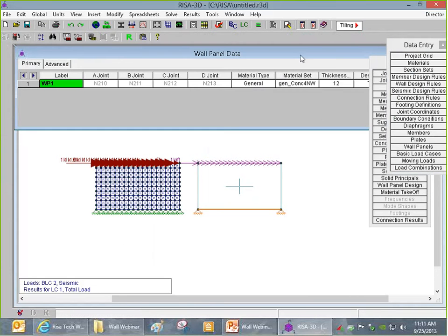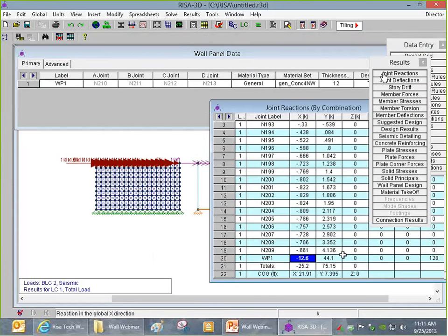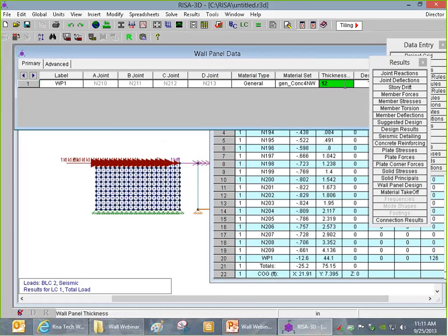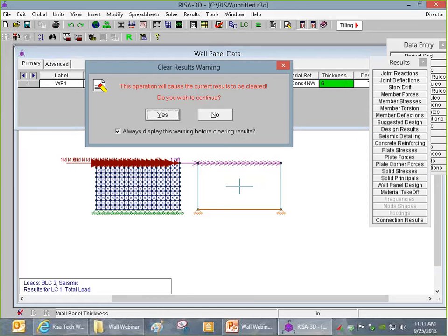Let me just come in here and check something. I noticed when I was in here that we were off in terms of the Y direction, the wall doesn't add up to half of what the plates are, and so that tells me right there my thickness is wrong. I wanted to do a 6-inch wall.